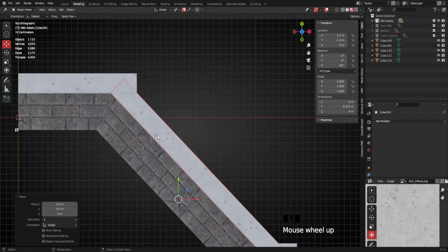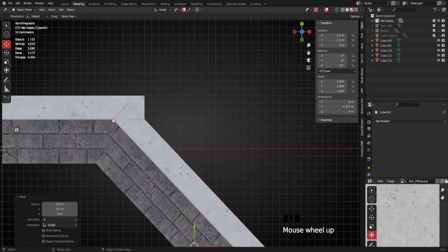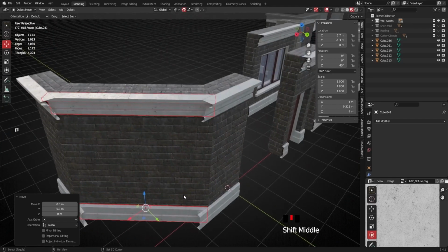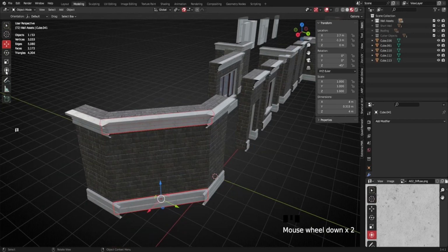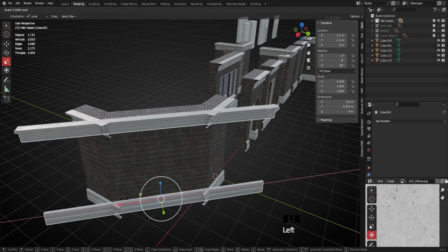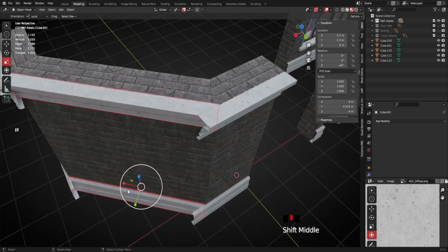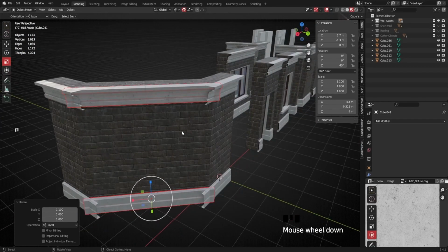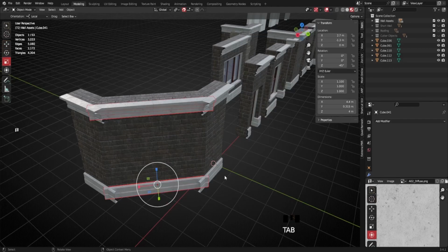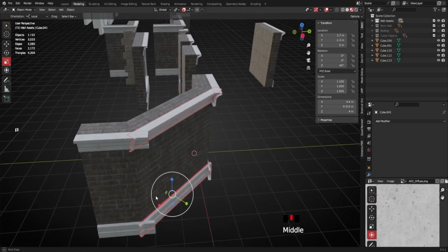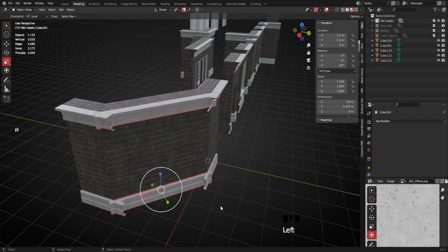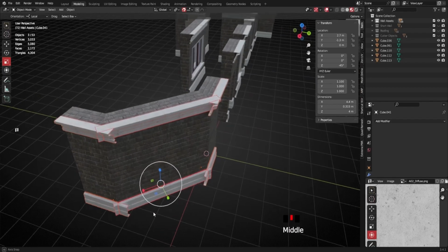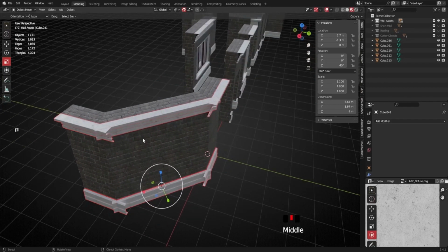Okay, so we have a slight issue here, being that for me to cut this way and join the verts, this needs to be longer. This has to be intersecting here. So what I could do is go to scale, and I want to make sure that my scale tool here is set in orientation mode, set it to local, so it'll scale along the axis that you want. And I'm just going to scale it on the X here until it joins at that point there, because we're going to cut through that. So with that, I can just select these two guys here. I want to keep this as the main because it's got the pivot point centered here. So I will select the two smaller pieces first, then the large one that I just scaled, and Control J, and they will inherit that pivot then.